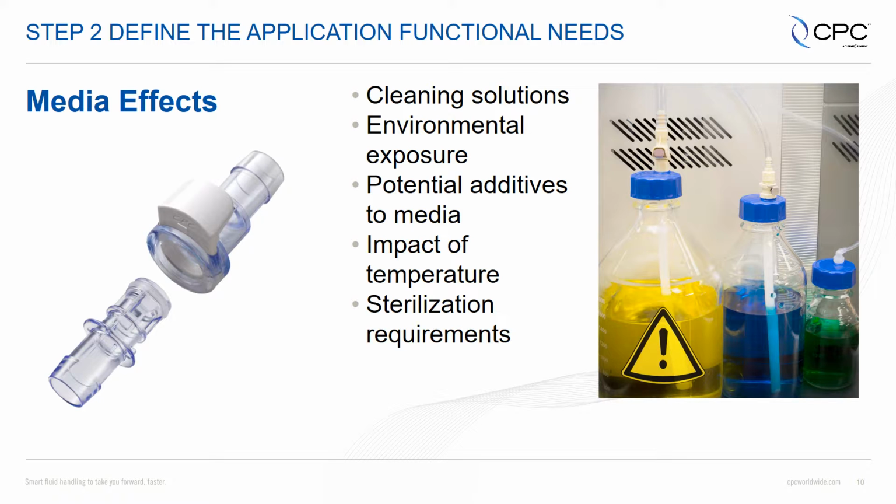When we talk about media, it's the chemicals that are going to be flowing through your tubing and thus through the connector. And we got to consider some other things though as well. We need to consider cleaning solutions. Is someone going to be cleaning this with an IPA wipe on a regular basis, or are there other aggressive chemicals or cleaning solutions? There might be environmental exposure, whether that's ozone or ultraviolet light, if it's going to be in the sun.